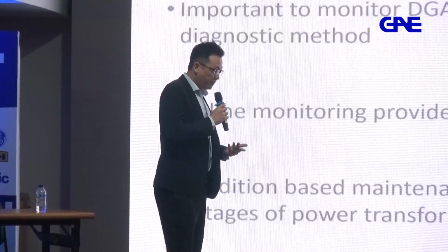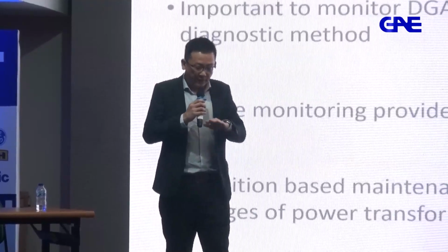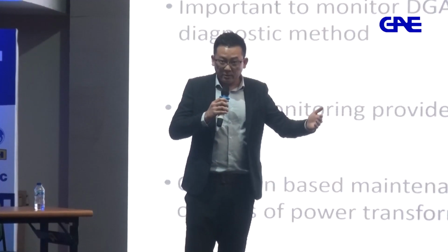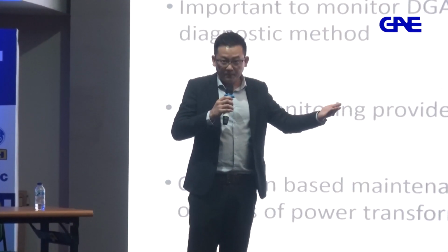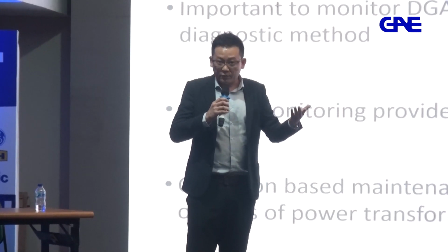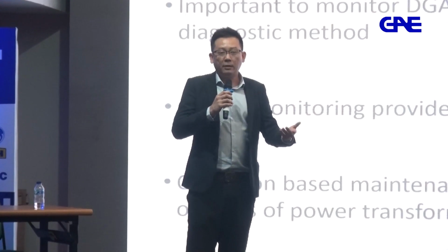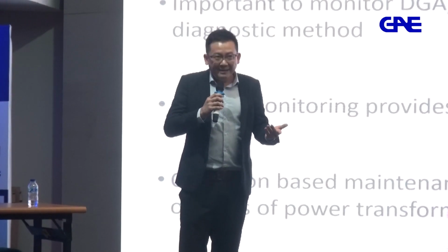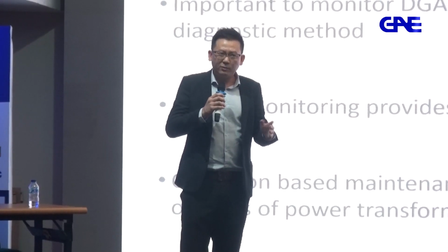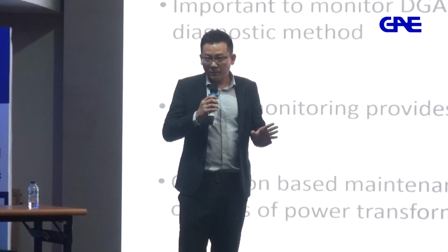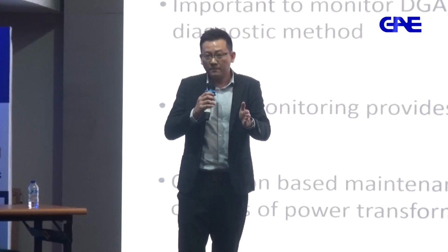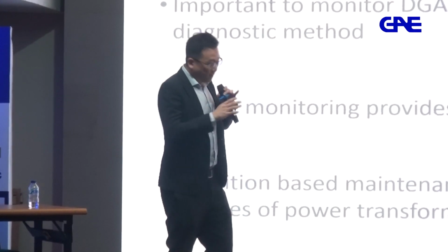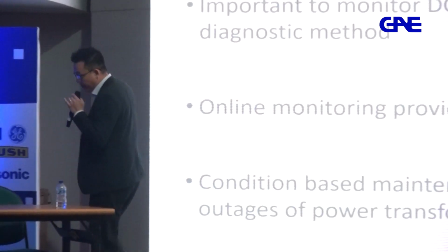If you ask how long it takes, in days or weeks, to identify a trend if there is really a fault with the transformer, we talk about accuracy and repeatability, at least probably 12 measurements. So half a day, 12 hours, and I can see a perfect trending on the gases already.